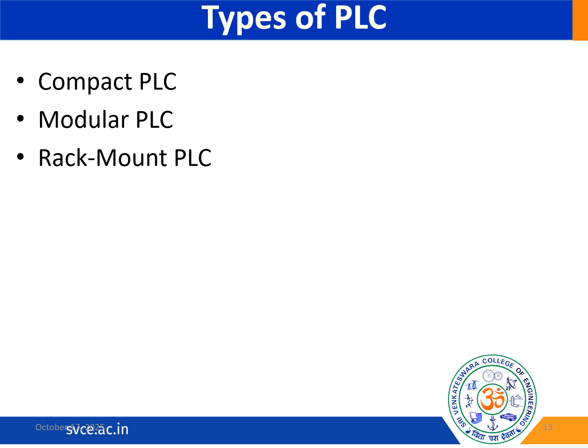Compact PLCs are small in size and have a limited number of input output pins. These are designed for applications where space is a critical factor and the control requirements are very simple. Compact PLCs are often used in small scale control applications where the number of devices to be controlled and monitored is very limited. Examples include simple machines, standalone equipment, or processes with minimal complexity.